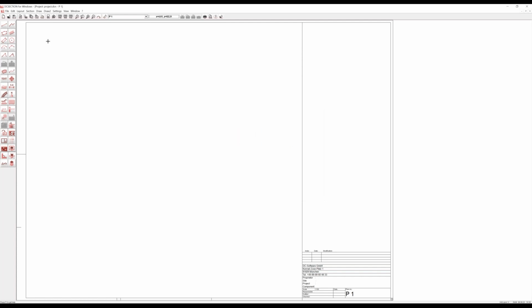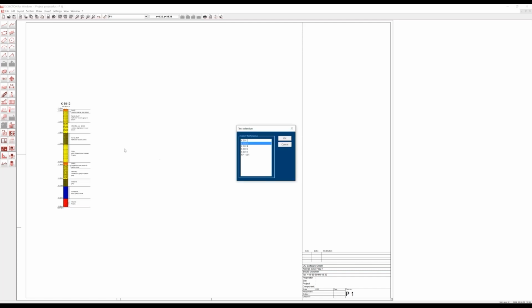So we want to use this project file and select one test, one bore profile, and this profile should be located at this position here. And this might as well be some reference point, so we can define an additional distance to this point where the bore profile is located. Then it is defined here, and then we can select the second bore profile. And now for the reference point, we can use the previous bore profile. I select this one in this red circle here.